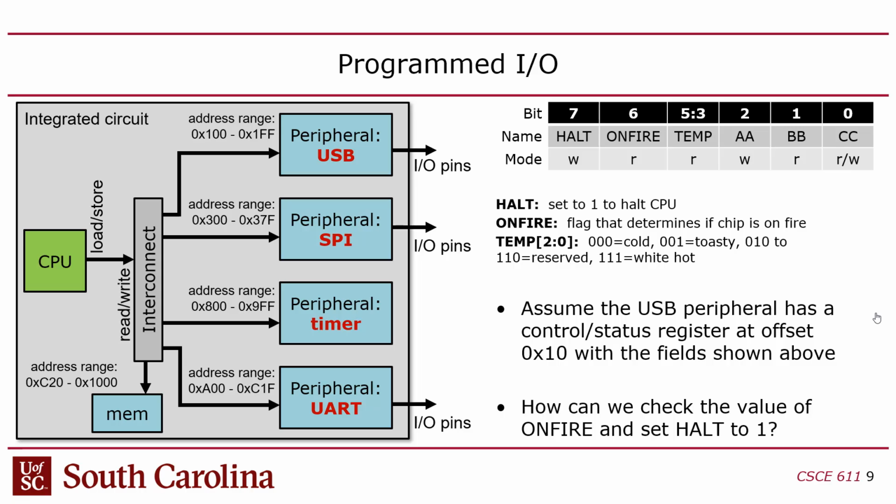Not always, but usually, each one of those registers will have bit fields associated with them. In other words, you can think of each control word like a C structure, like a struct, or like a Java class with members in it. But each one of the components inside there is defined by a range of bits.